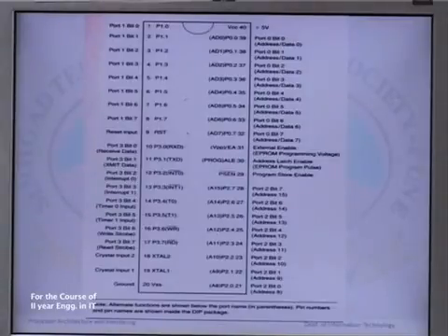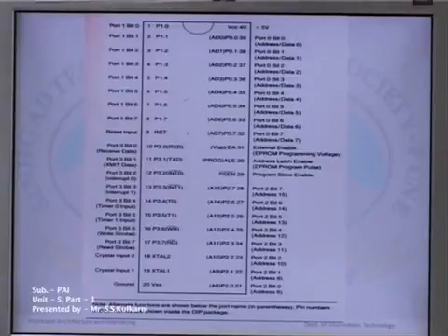In case external memory is used, the higher address byte, that is addresses in the range A8 to A15, will appear on this port. Even though memory with capacity of 64 KB is not used, whenever we are using external memory of size less than 64 kilobytes, then the remaining port bits are used for the input output operation and the required ones are used for the addressing.